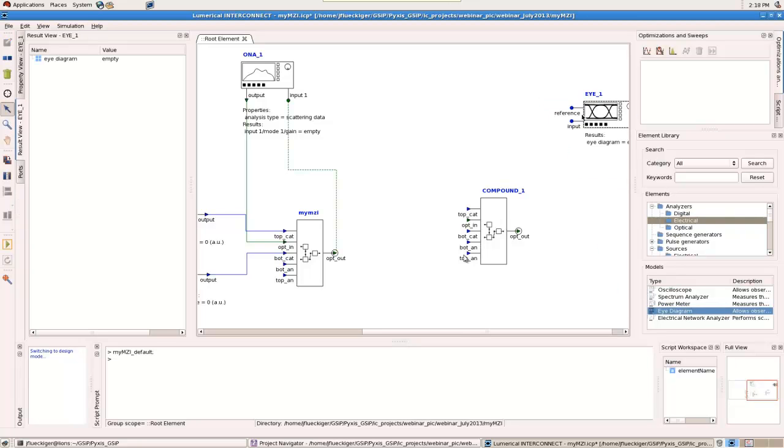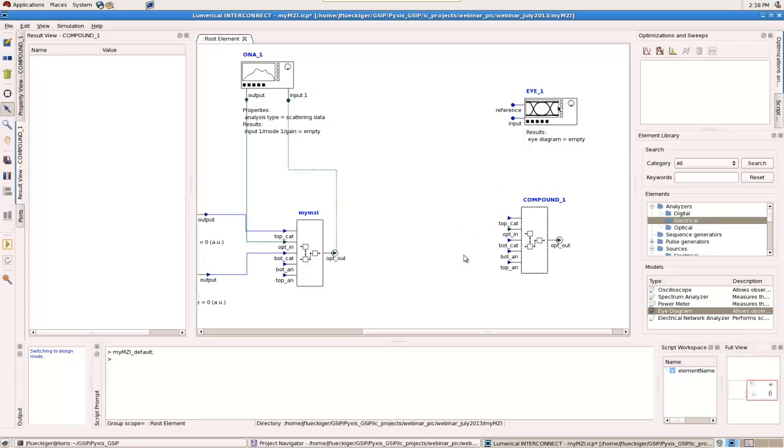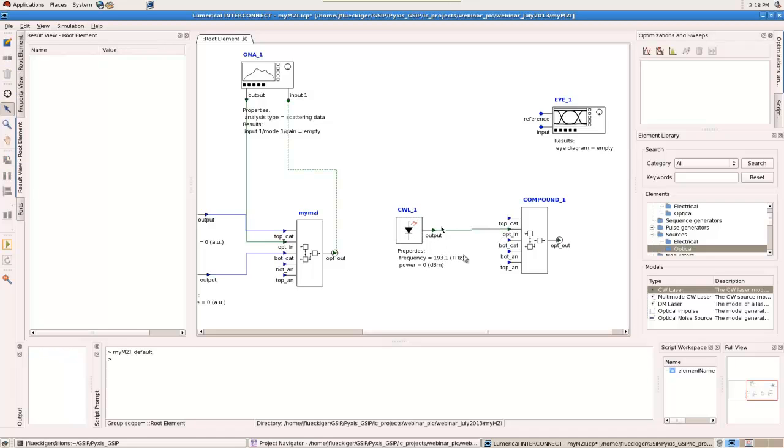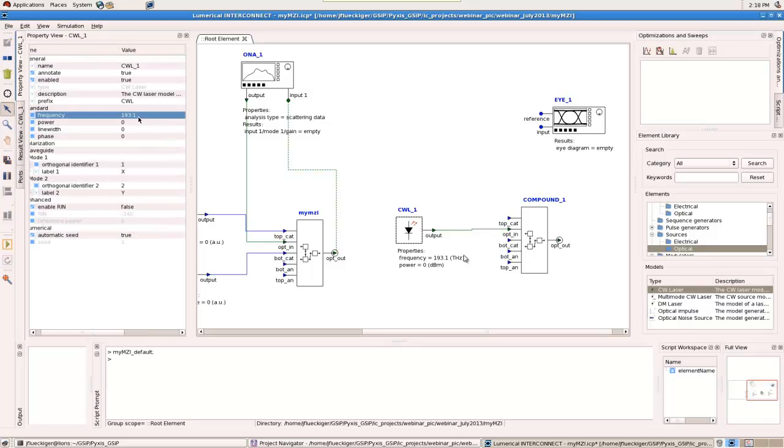So I'm going to use an eye diagram. I think it's a good way to see it, the classic time domain measurement. We are starting here actually by the receiver side, so we're going to get the eye diagram. We're also going to choose a photo detector here. We set our source, and in this case we're going to set it to the input, and then here we're going to set that frequency value we measured before. So we set 0.65.